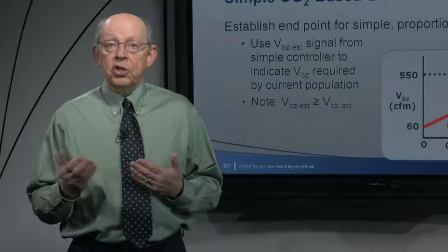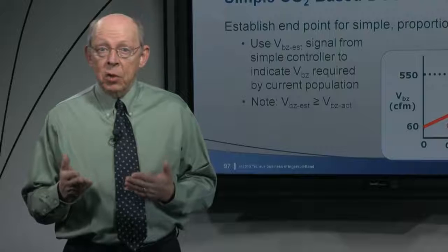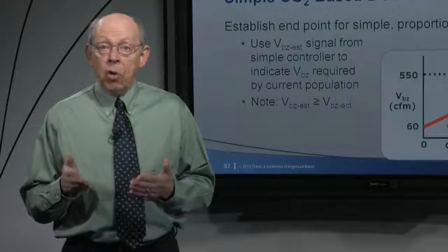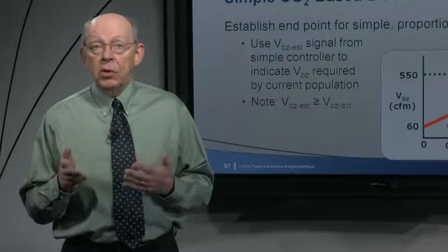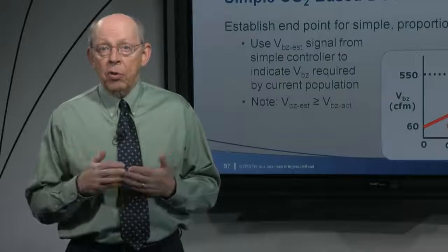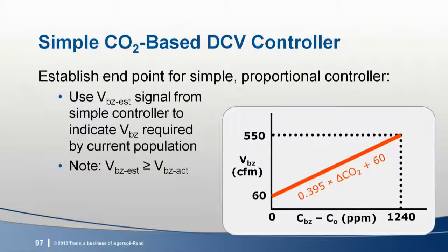This corresponds to a change in required outdoor air intake flow for both single zone systems and demand control zones in 100% outdoor air systems, and it can be used to modulate outdoor air dampers directly in those systems. Modulating the outdoor air damper, of course, changes the differential CO2 level and estimated outdoor airflow rate.